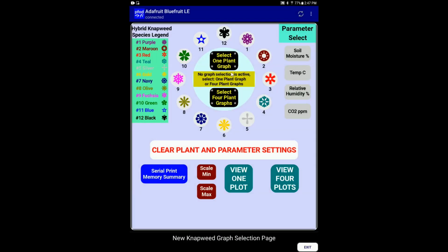Now there's a couple ways to save data. You can send it to a FRAM memory chip, which is only 32 kilobytes. So there's not that much memory capacity there. Or you'd send it to an SD card, which most people probably use for data logging with a microcontroller. And send the information to one of those 2 devices, and then pull the information off those devices when it's time to have a look at it.